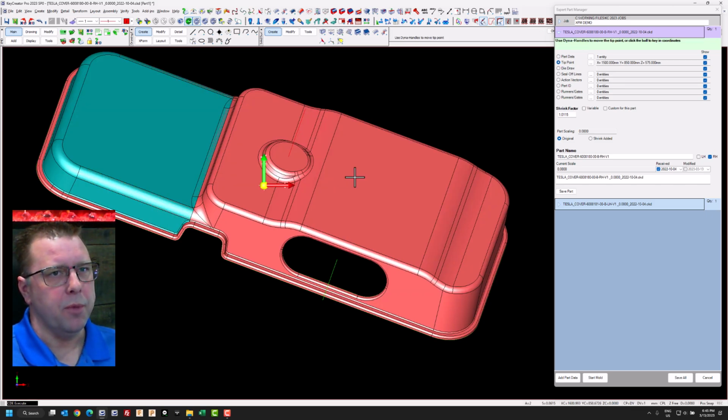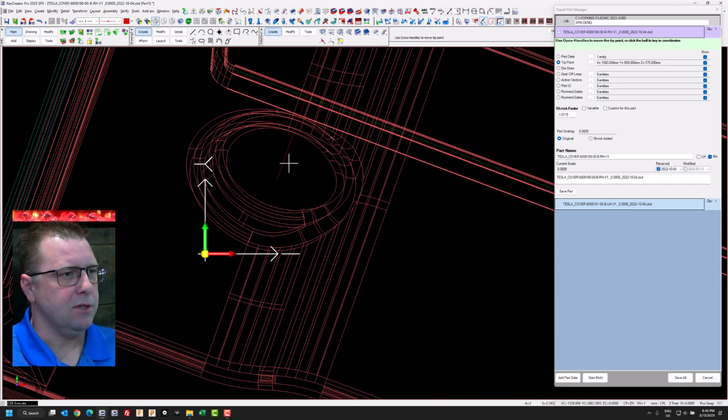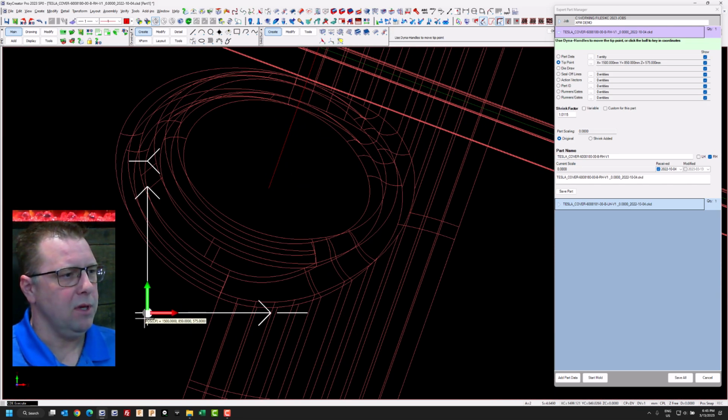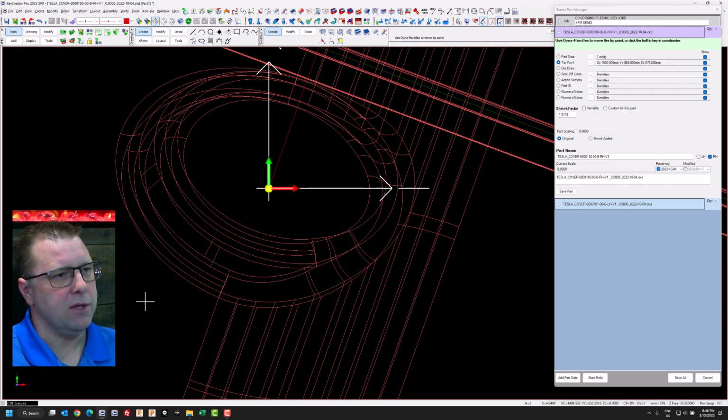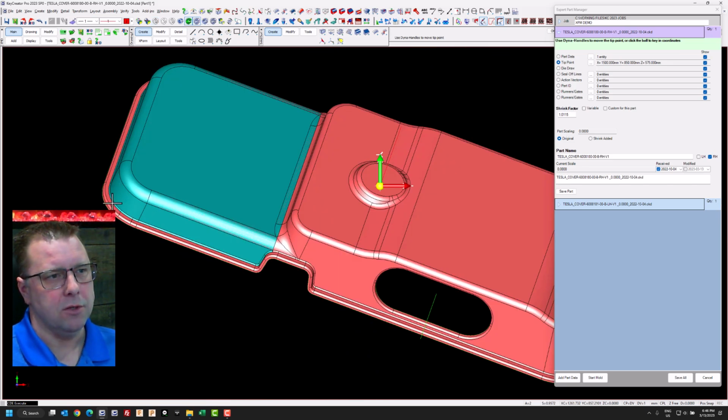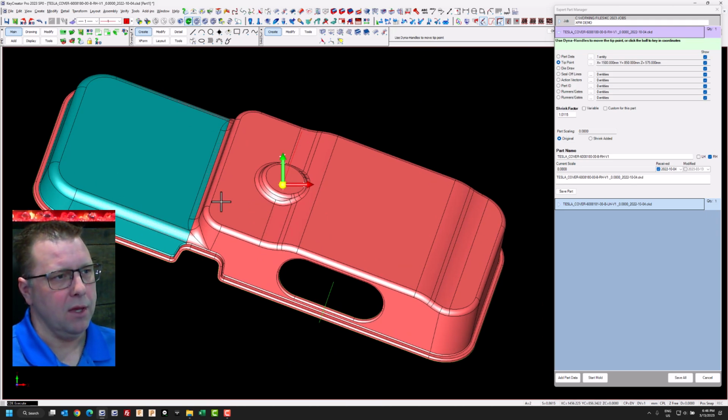Now we are going to pick the tip point location. It's optimizing based on the center of the mass of the part. In this particular case, I want to move it over to where this drop position is going to be. For a round part, you might want it at the center of the round, maybe at a bottom flange, but that didn't happen to be center of that particular part. You're free to move this wherever you want. Notice that when it did select a location, it picked the center of the mass, but it ensured that it made it a nominal location. So of course in mold making, in particular die design, that type of thing, we do like nominals often. So it automatically had done that for us.